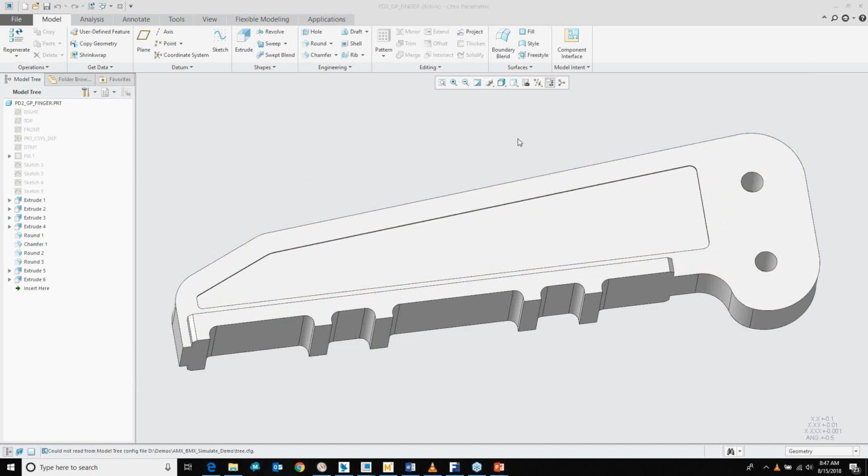And so there have been some prior analyses that have been run, and we've already come up with some specified or targeted center of gravity calculations that we want to hit, in this case with Creo, right? And in addition to the center of gravity calculations, we also want to make this as light as possible, right? So again, the lighter this arm is, the less work the motor has to do in order to move the component, right?